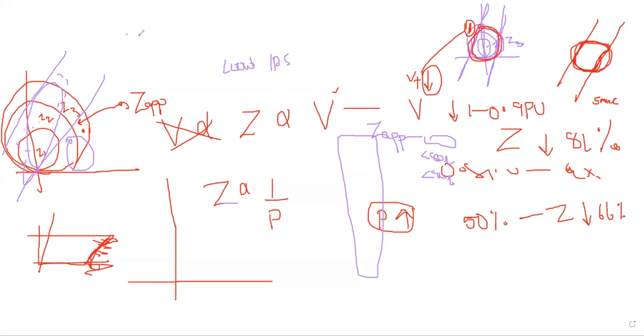First of all, when a fault occurs, I will check whether there is a voltage drop. If the voltage drop is there, I will block this. Then the relay will check which zone, zone 2, zone 3, zone 1, it will operate. If there is no voltage drop or negative sequence current is flowing, some characteristics, then I am enabling this one. So then our relay will operate only inside this part.